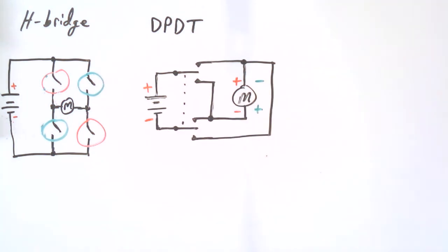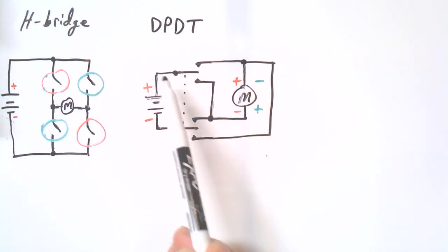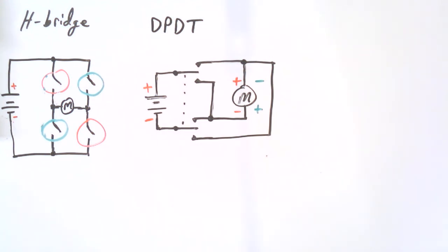It works the same. I forget if I mentioned it, but these contacts could be relay contacts. I think I might have said it over here. But again, to get it back in our heads, that could be a DPDT switch. Could be a slide switch, toggle switch with a center off position. It could be a relay also. Now, a relay doesn't have a center position, or the ones we have at least. But it could still be a polarity reversal.